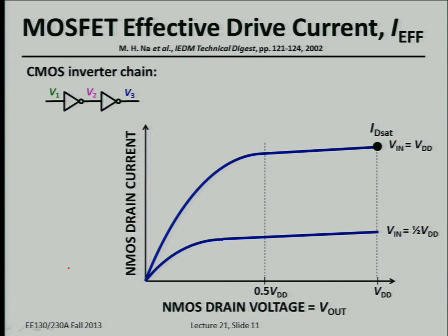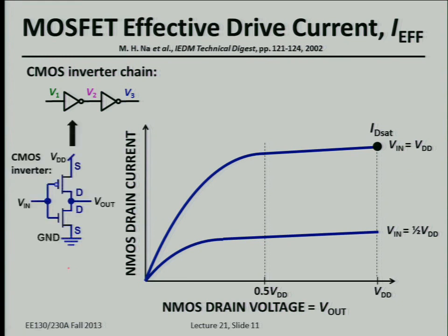So let's look at a digital logic circuit. You usually have an input signal driving the input, and the output of some logic gate driving the input of the next stage. A simple example is just inverters connected in series like this. Each of these inverter symbols just represents 2 transistors connected in series like this.